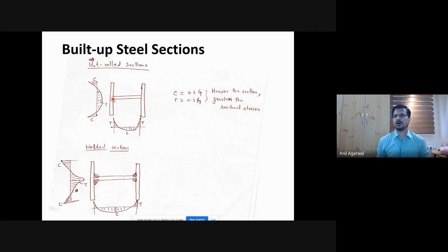So this portion is still hot, and the steel is also gaining strength. Let's say this steel becomes much cooler, this is still hot, and the shape is finalized. Subsequently, when this steel also starts to cool down, it wants to shrink. But this steel, which is at a much lower temperature, does not want to shrink with it, because it is solidified.